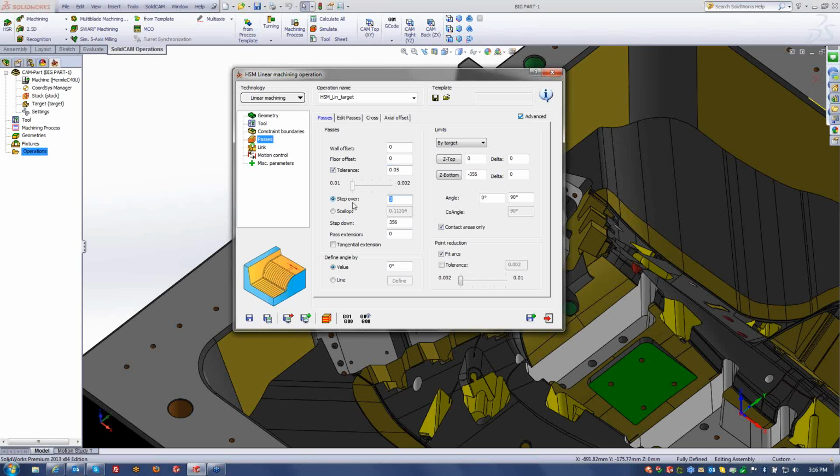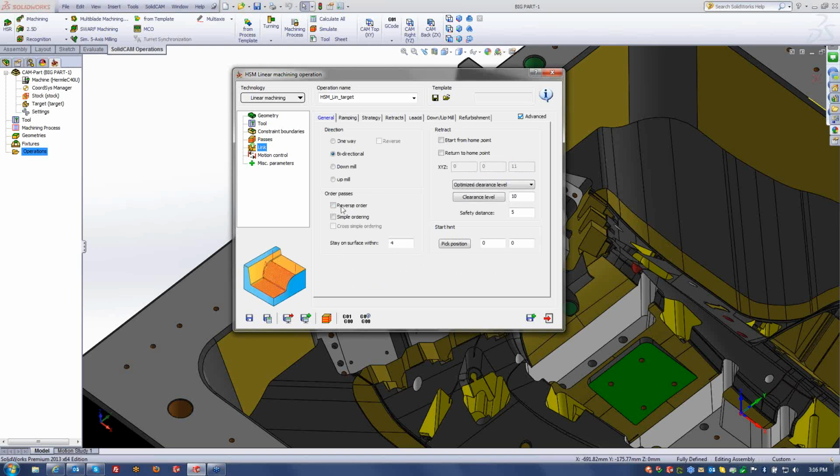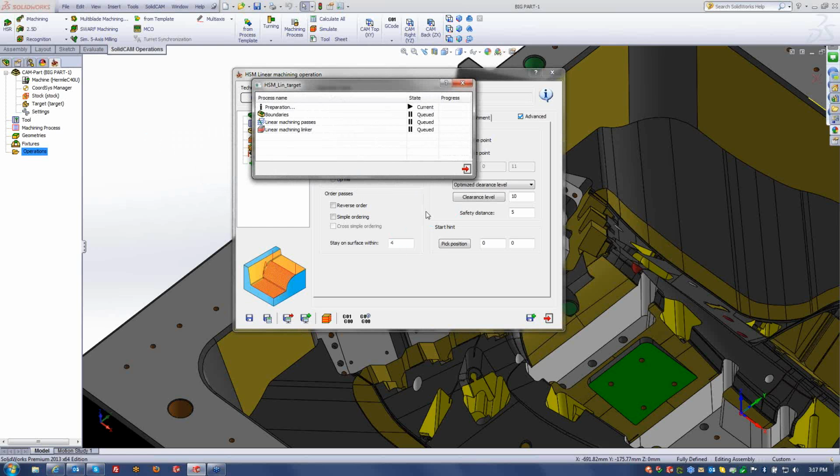That means, of course, we can work at 45 degrees, B direction, and we can calculate. Now we generate the STL. Of course, now the STL works faster when we generate. And now after this we start to calculate the passes, the link. Of course, you can see now it takes more time for the first part, because we have here more surfaces and more curves, but generally it works very, very fast.